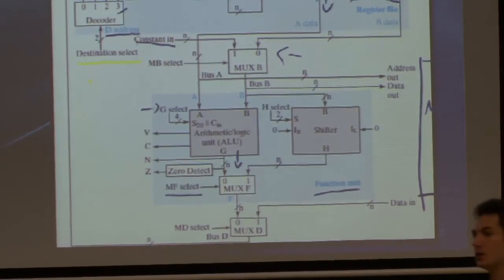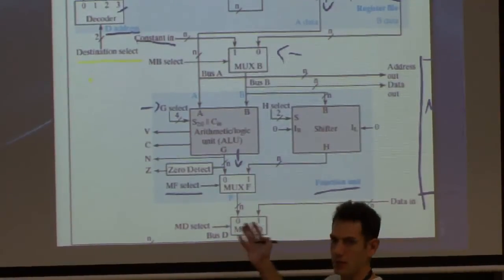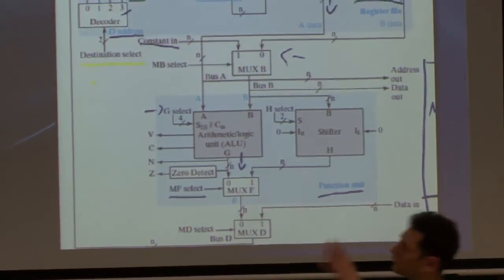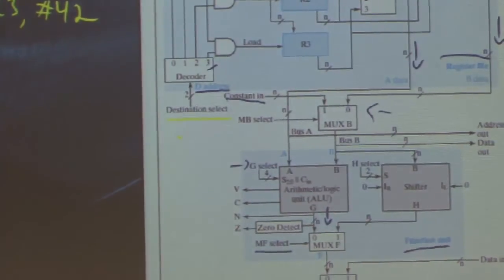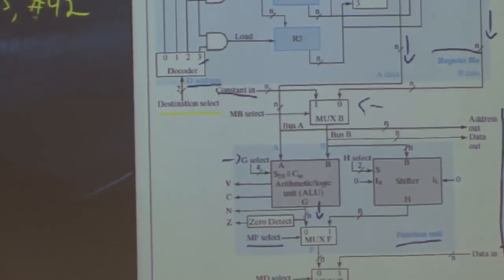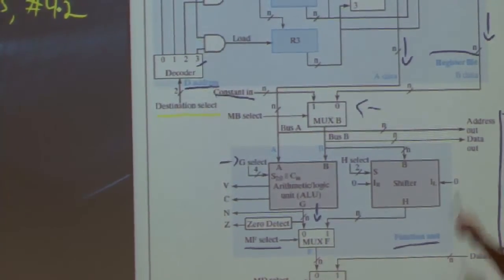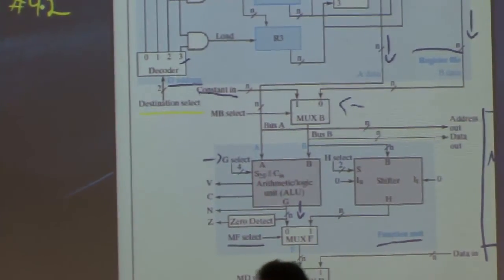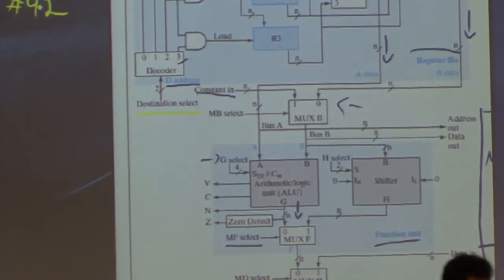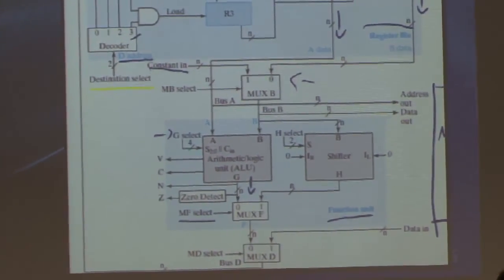3. So that's another way of manipulating this data path to do exactly what we want. On the same token, I could have just copied another register, say R2, into R3 by choosing, instead of a constant, another register. Another example.